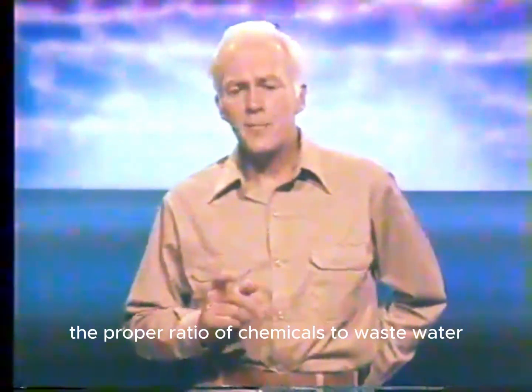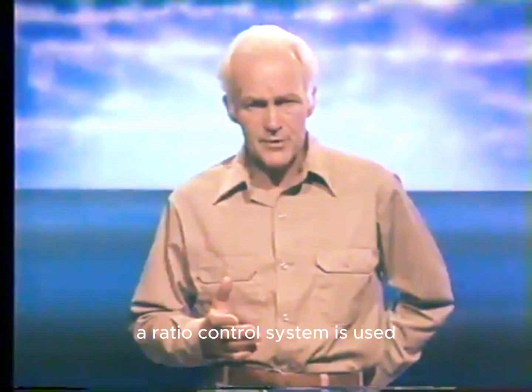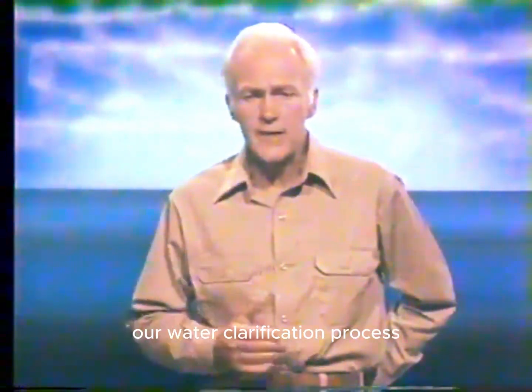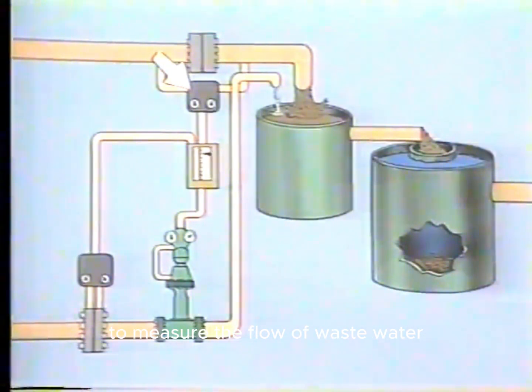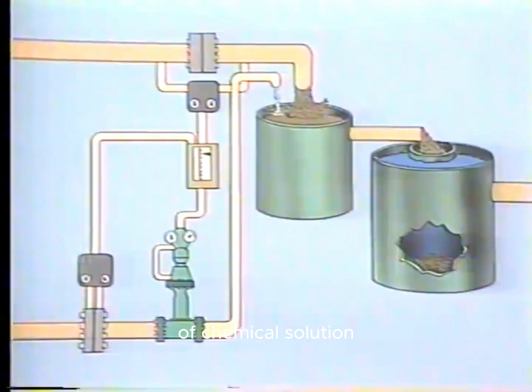To maintain the proper ratio of chemicals to wastewater, a ratio control system is used. So let's add a ratio control system to our water clarification process and see how it works. The control system for this example includes a flow transmitter to measure the flow of wastewater and a flow transmitter to measure the flow of chemical solution.